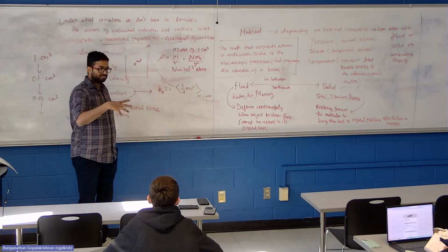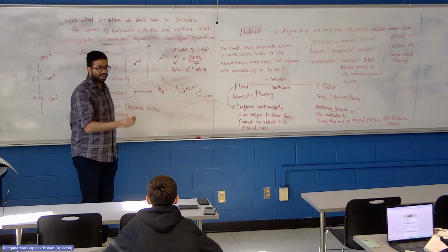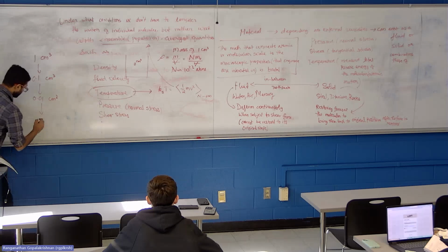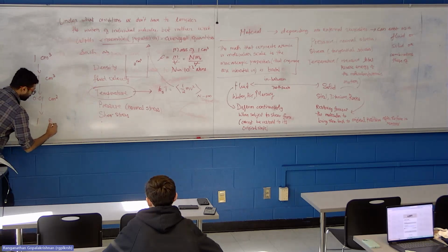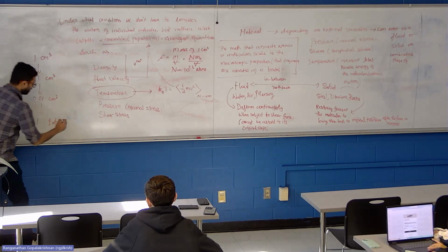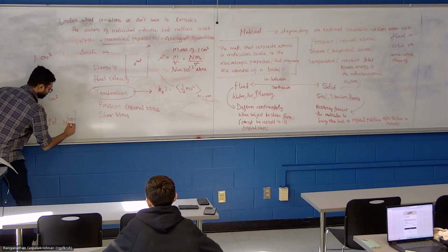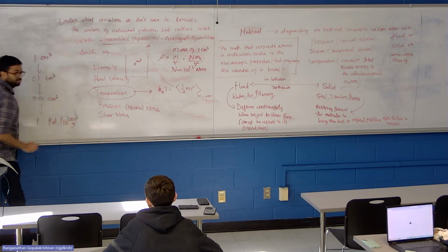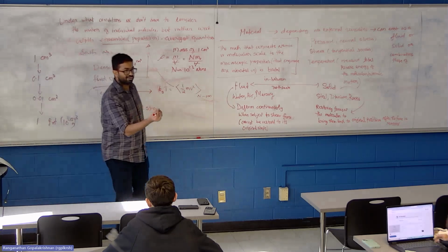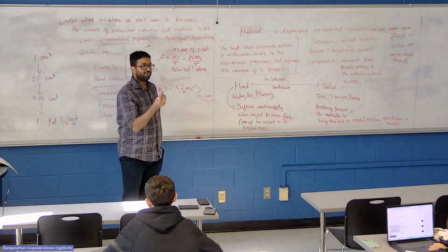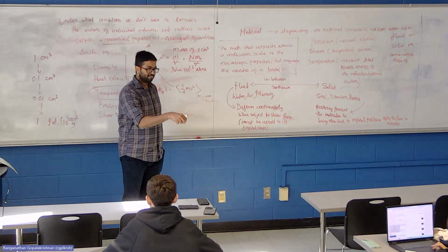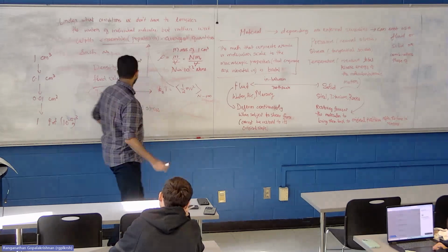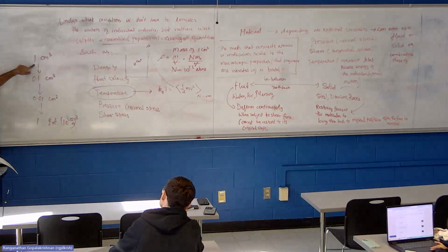that this density estimate will start to fluctuate. If you go really tiny, let's say you go down to 1 femtometer cube, which is about 10 to the power minus 15 meters cubed, you'll hardly find a couple of atoms in that little volume. And if you measure your density there, you will get an answer that is not the same answer that you will get at this scale.